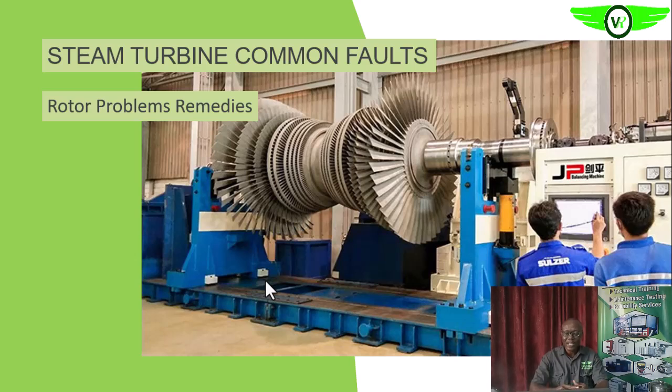So what are the remedies? How can we remedy the situation when we have rotor problems? Let's look at unbalance. Like we said earlier, unbalance is something that will show up at one-times RPM vibration. That is vibration frequency information. Are we getting it? If you are not familiar with it, you can check our training on vibration monitoring and analysis under equipment condition monitoring, or under vibration analysis, on our playlist.